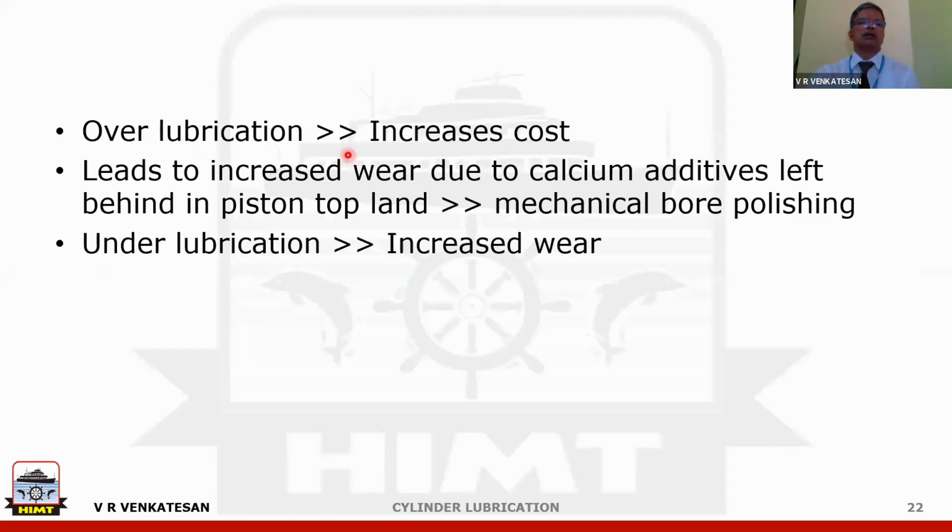Now, one of the mistakes made in a lot of vessels is the assumption that if it is possible to send more lube oil, it is better. Or say, the more lube oil I send, the better it is. That is applicable in the case of a journal bearing. In a normal journal bearing, there is no harm in supplying a lot of oil. But in the case of cylinder oil, there are two problems. Number one, cylinder oil is a consumable item, so definitely cost will become higher. More than that, even if the cost is not a problem, you have this issue that wear rate will actually increase due to scuffing. And this is because of this.